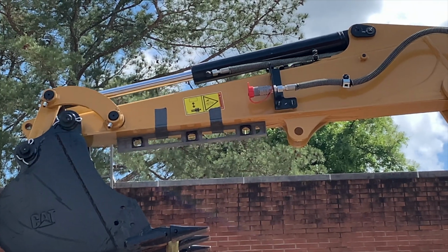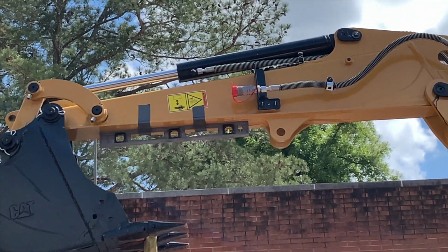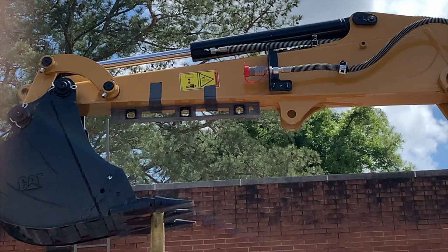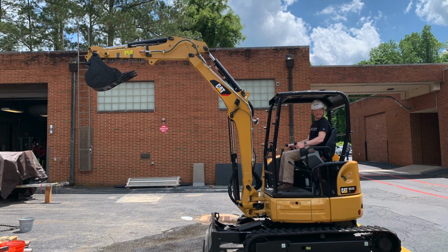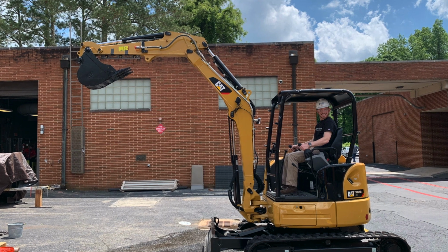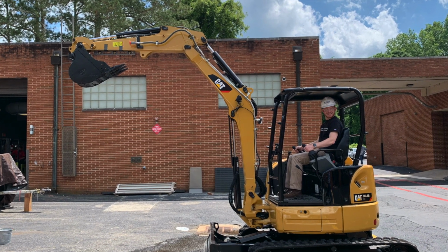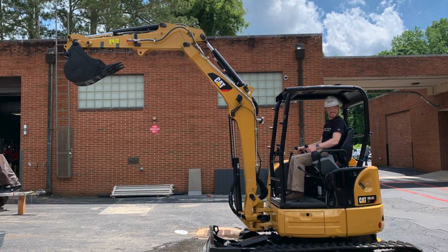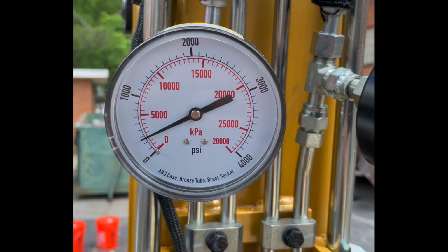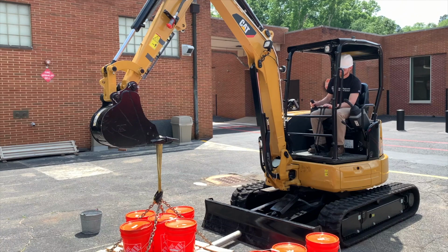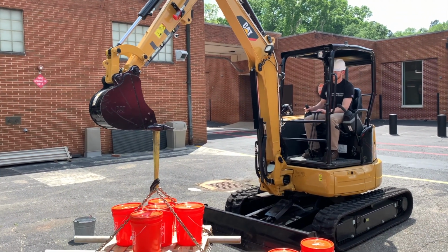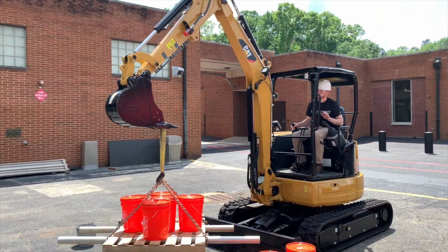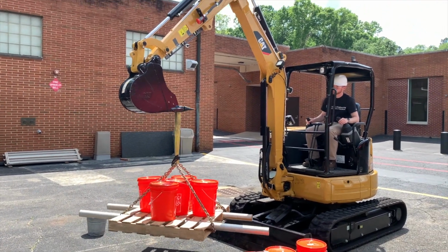To do this, we attached a 2-foot level to the stick and could see the bubble from the ground to ensure that we were getting back level on every single load. And the first thing that we had to do to make this as accurate as possible was to develop a calibration load, which was a no load situation in which just the arm of the bucket was lifted to the experimental height and the pressure was read, and then that pressure was used on every other load that was attached, and the pressures were subtracted from each other to develop the pressure needed just to lift the load itself and not the arm of the excavator.